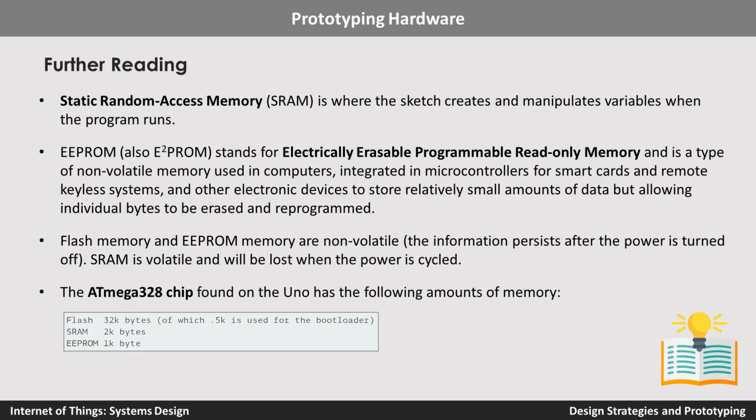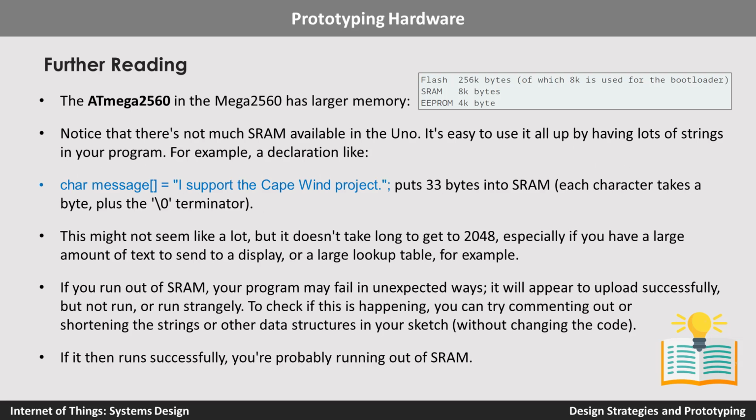It is one of the commonly used Arduino microcontrollers by entry-level or novice people. In that particular chip, you have 32 kilobytes of flash, out of which 5K is used for the bootloader. Then you have 2K of SRAM and about 1K of EEPROM. Another type of chip is ATmega2560.